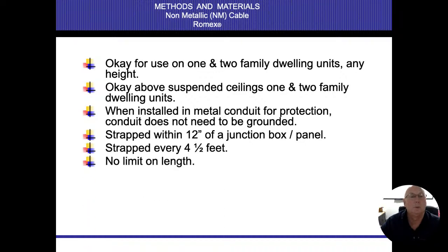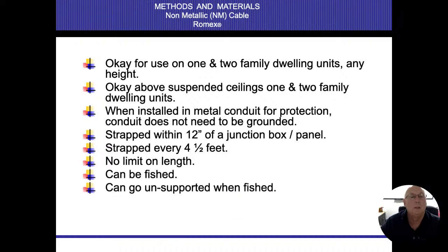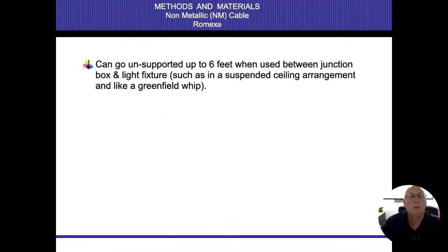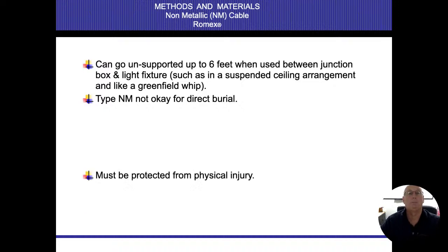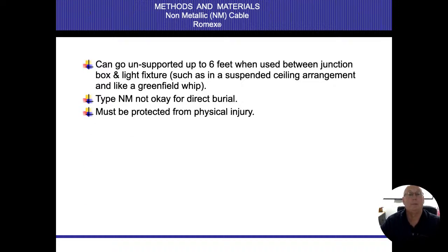12 inches, 4.5 feet, no limit on length. It can be fished. Doesn't have to be supported when you fish it. 6 feet, basically same rules as Greenfield. Type NM is not okay for direct burial. We do have to protect it from physical injury.